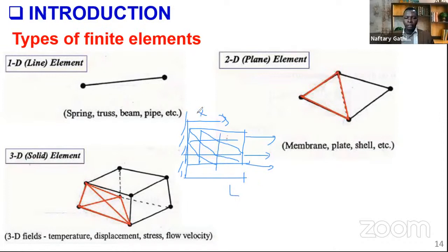the strain or stress distribution, in terms of contours. So what we are saying is that you need to calculate the stresses in element 1, element 2, element 3, element 4, like that. And in each of the elements, the strain is constant. We call it the constant strain triangle, right? So that's just an overview. But let's see it in application.